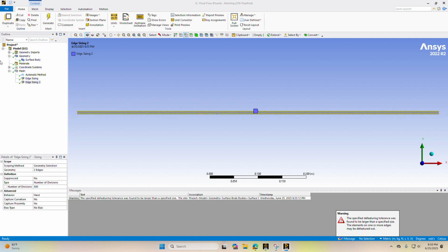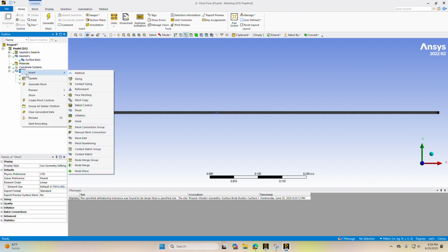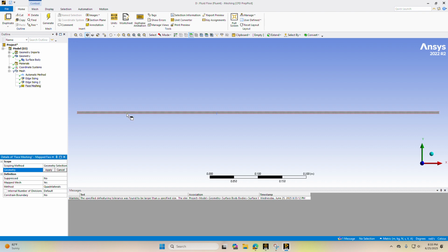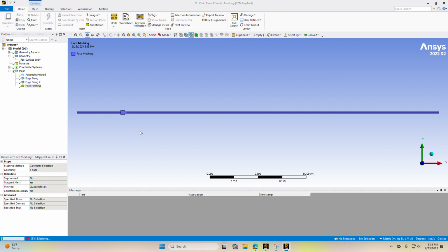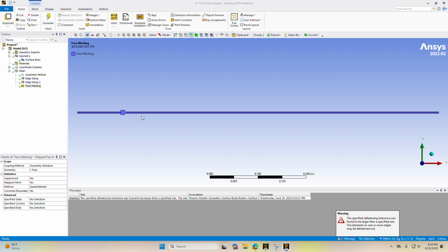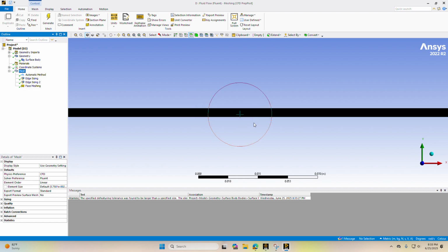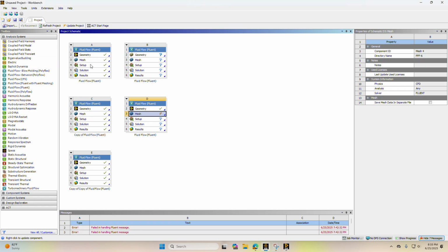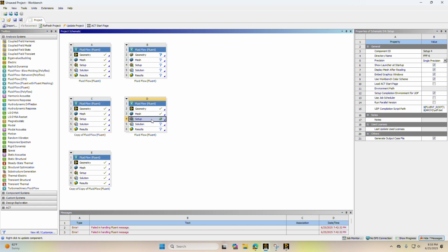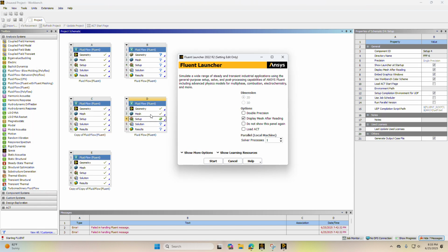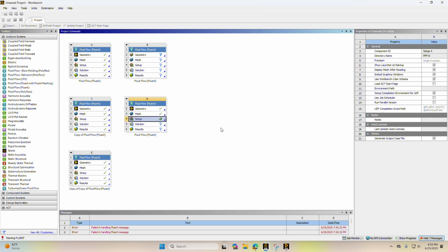And we should almost have our surface. We just need to do once more face mesh. Select this, apply, and then generate. Okay, so I think once we click out of this, we should see our divisions. That looks about right. Go back into our document, update this task, and then head straight into setup while using double precision and selecting start.